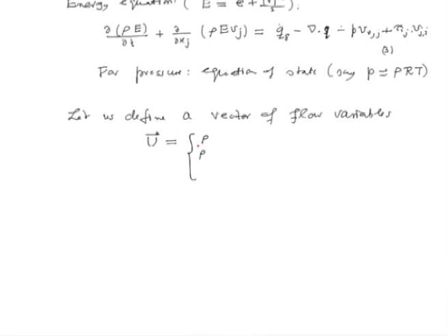So the primary unknowns are, let us say, density for the continuity equation; for the momentum equations, using Cartesian components, rho u, rho v and rho w; and similarly the last equation has rho capital E. Please be careful here, we have not used u, v, w and E, we have instead used the combination rho u, rho v, rho w and rho E, and getting the primitive variables u, v and E would be easier once we get these components.